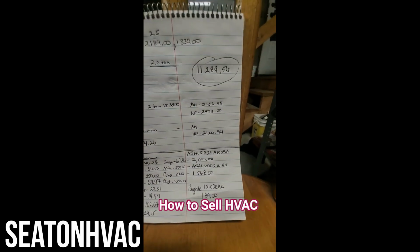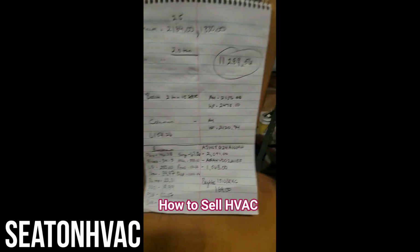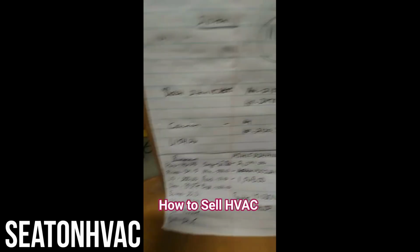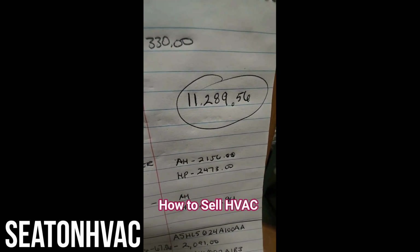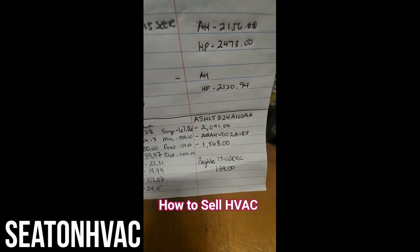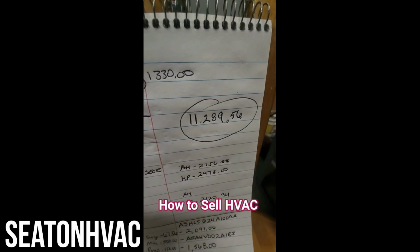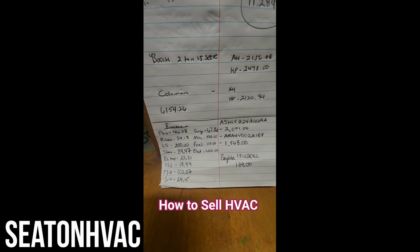Okay? Now when I'm busy, I'll divide by a 0.5 divisor. That basically would double that. So the job would have been 12,000 and some change, 12,300 something. When I'm slow, I do 0.6. It'd have been less than this number. I did 0.55. This is my sale price, $11,289.56 for a 2-ton heat pump replacement in a manufactured home. Simple line set. Makes a lot of sense, doesn't it? And the job's already sold. She didn't even blink. So that's how you bid stuff. That's how you are successful. Do things properly.